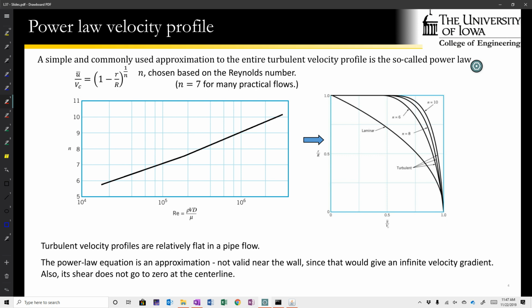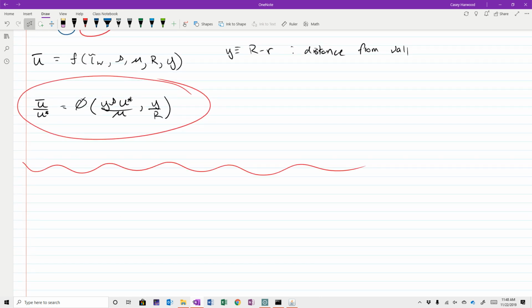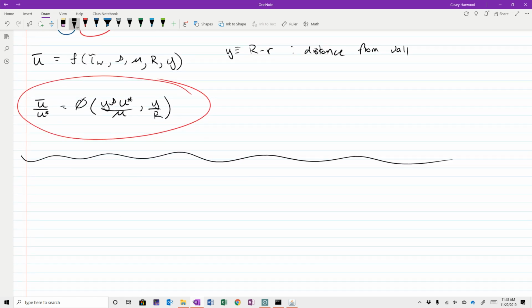So the main topic, though, and this is what I wanted to introduce, make sure that we get through today, is the topic of head loss. So in the energy equation, we saw head loss as sort of a mysterious h sub L that was given to you. 2.5 meters of head loss, 1 meter of head loss, ignore head loss, right? But where do those numbers come from?